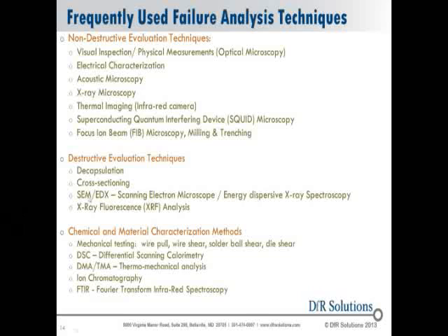Very often we'll use scanning electron microscope and energy-dispersive X-ray. You'll say, why is a microscope destructive? Well, you have to cut up a very small sample of a device and put it in a vacuum chamber. It's not like you can take an entire electronic module or circuit board and put it underneath the lens of your microscope, because there are very small chambers that these things will fit in. And then there's X-ray fluorescence analysis, another one.